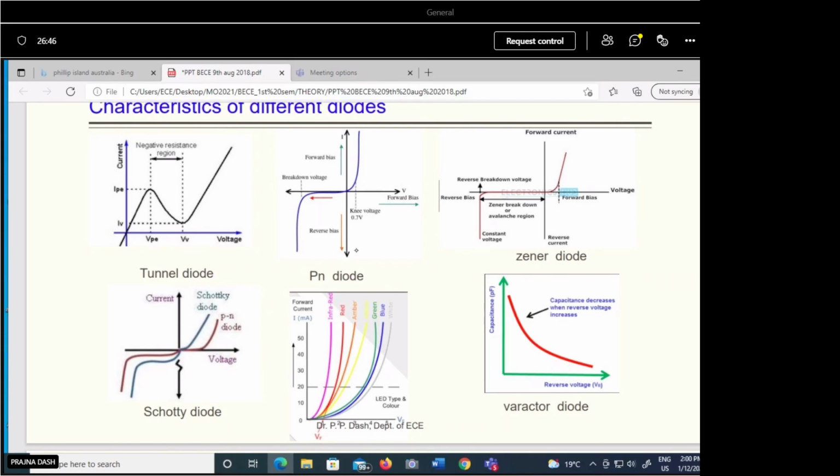Usually in the normal p-n junction diode we operate the diode in the forward biased mode. In reverse bias mode, beyond the PIV it is not possible to operate the diode because it will be damaged. Within this PIV range, the diode has almost zero current, which is very small in comparison to the forward biased current. So forward bias mode is used for a normal PN junction diode. But in the case of the Zener diode, we have the utility in the reverse region. Whenever we require a fixed amount of voltage for a particular maximum current, in that case we can use the Zener diode.